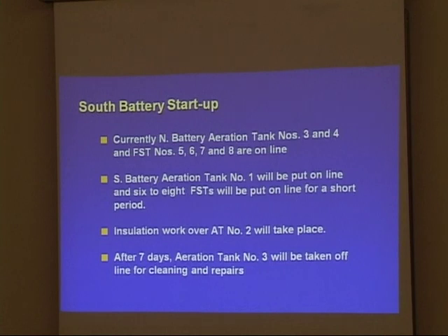Okay, so now we get into the south battery startup. We're currently using tanks 3 and 4 of the north battery, and final settling tanks 5, 6, 7, and 8. What we're looking at doing, I don't know about tomorrow, we'll see, is to get south battery aeration tank number 1 put online, and eventually, gradually, work up to 6 to 8 final settling tanks being put online for a short period.